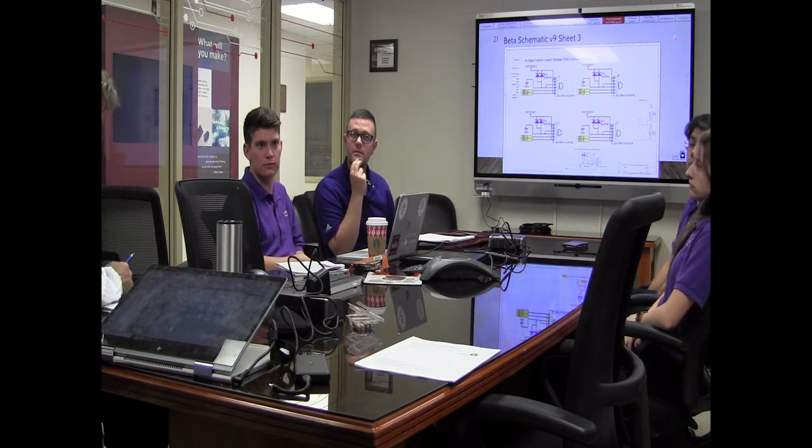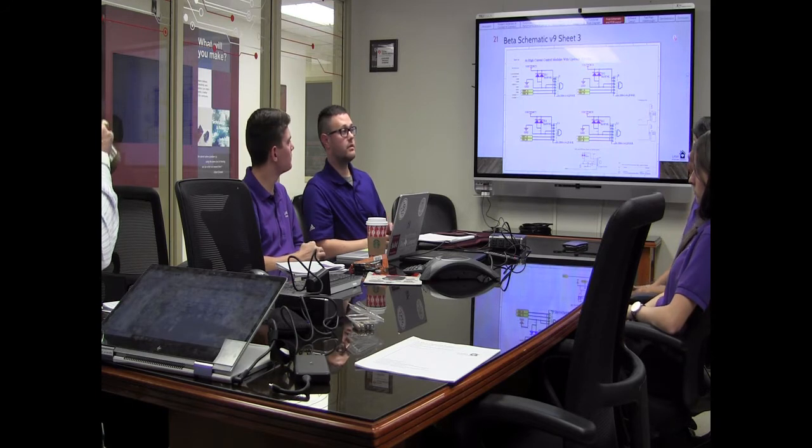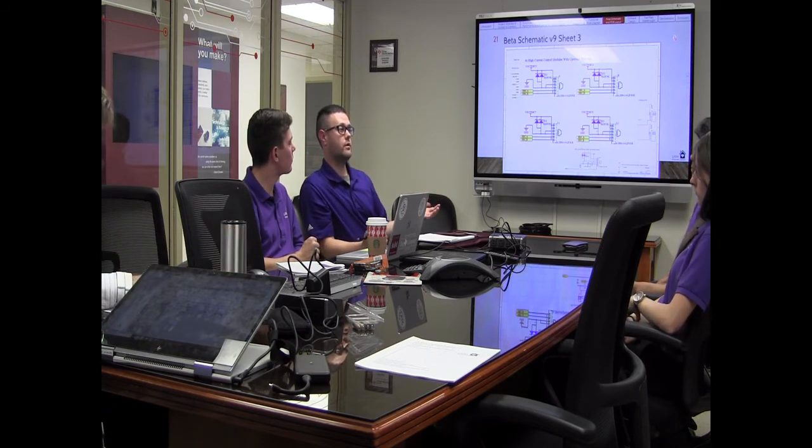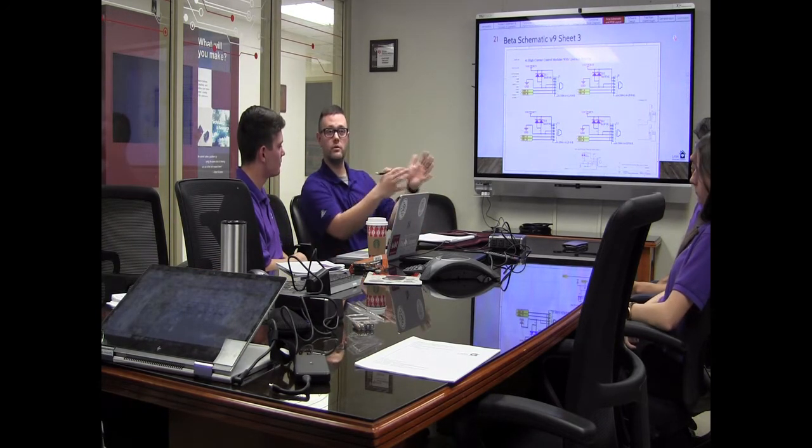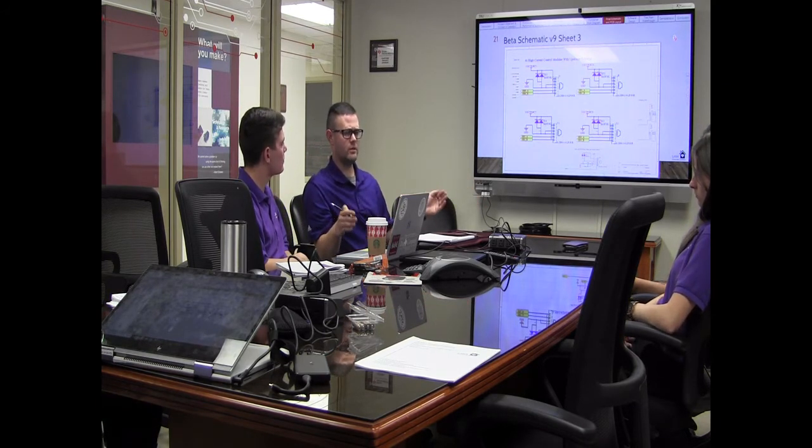Is your motor rated for this much current, or do you want more? No, that was kind of an extra step. It's designed for an unknown use case. Anything we're driving today in our demos with those LED strips was about 350 milliamps. What's the per pin current rating on an RJ12? Per pin is 1.5 amps with a max peak of 3 amps. Okay, so we're well within the current rating at 200 milliamps.